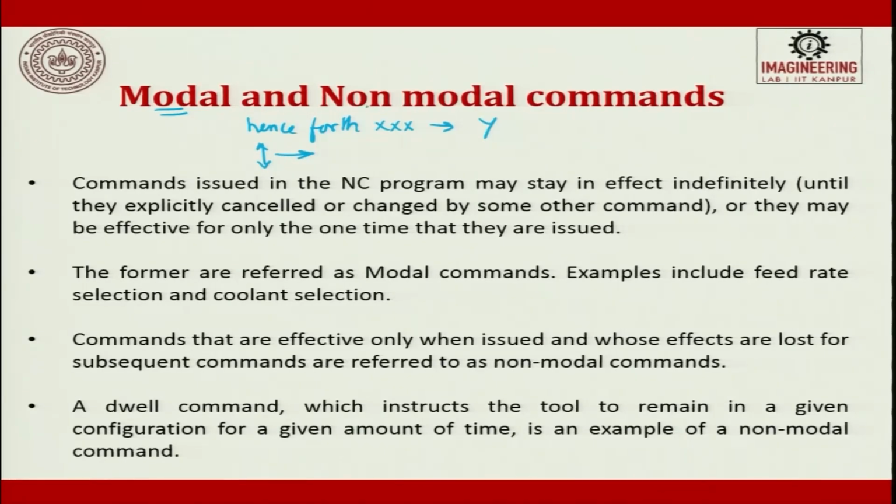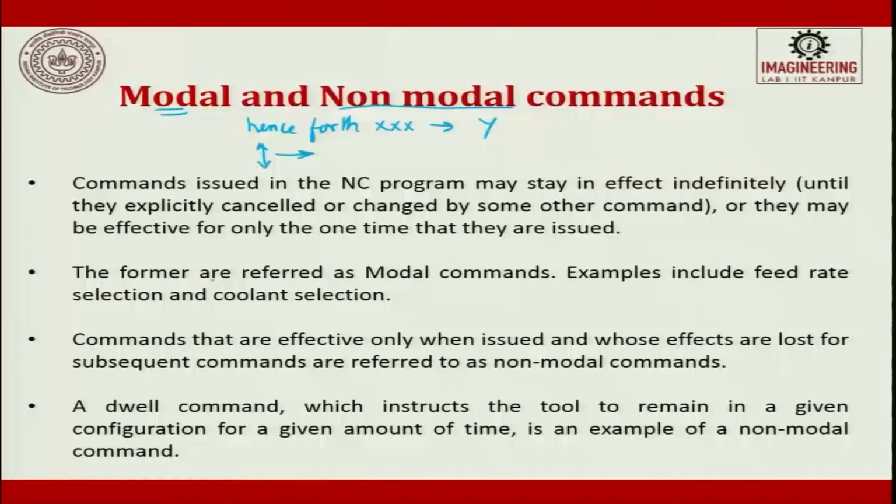Okay. So, then it is called as non-modal commands. Modal commands, once activated, you have to go back and say deactivate, then only it gets deactivated. Non-modal commands work for that particular part of the program, a subroutine of a program, and then get deactivated of their own. We will see more details when we see the program. The former are referred to as modal commands.